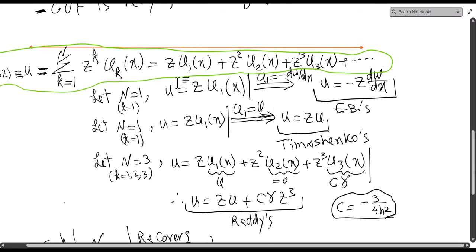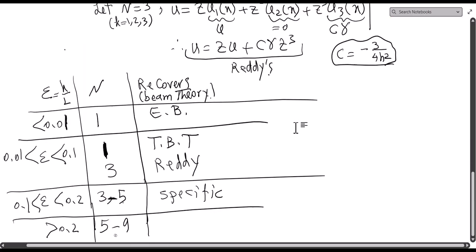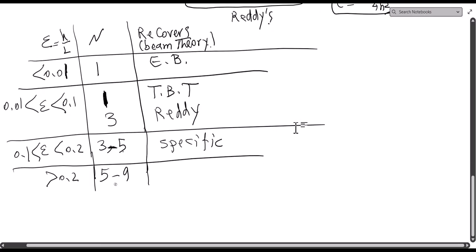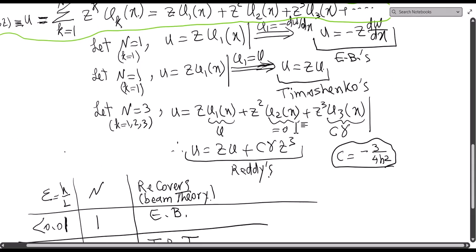You see that very easily, and this is mostly for laminated beam or multi-material beam, very easily by adding terms to this or picking more terms of this series, you will add much more complexity to your beam theory, but sometimes it is necessary to recover the physics of the beam and how the beam behaves. And this is the beauty of CUF, Carrera Unified Formulation.